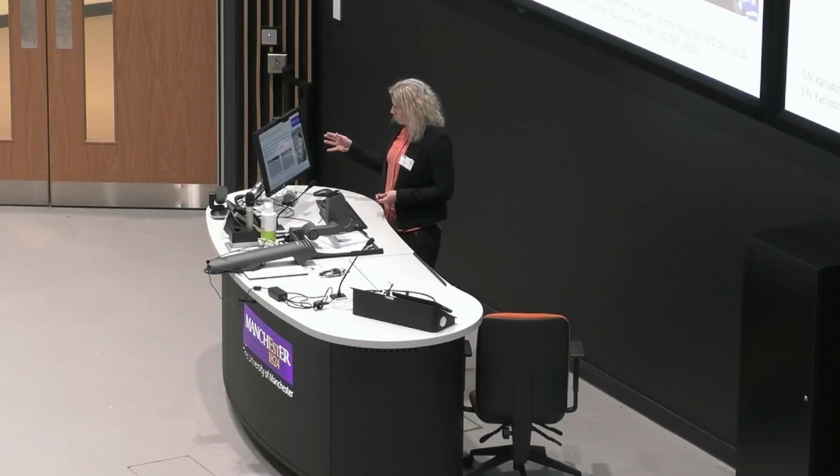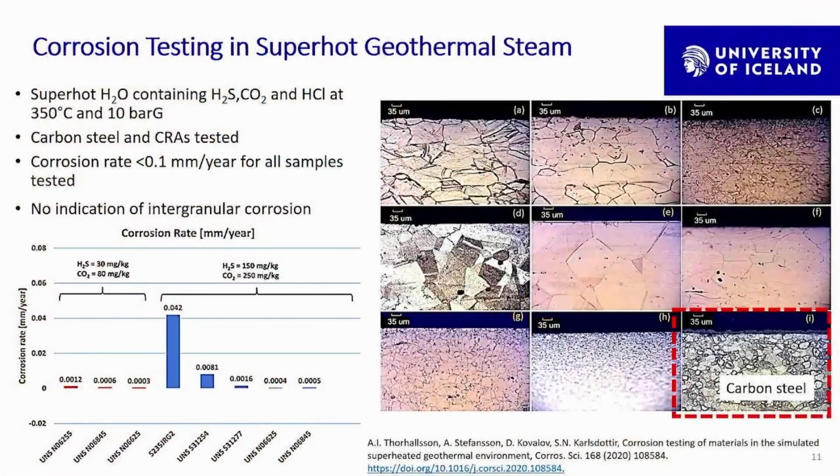After the flow test, actually the well had to be cemented and closed because of corrosion problems in valves. The stem of the wellhead broke, so with further inspection, the carbon steel casings had failed in multiple locations, most likely due to thermal cycling of the well, as well as the extreme temperatures and conditions. So the well had to be closed. Our opportunity to explore more was done for our research aspects.